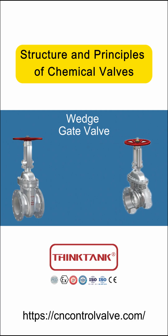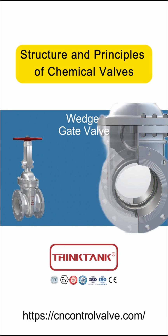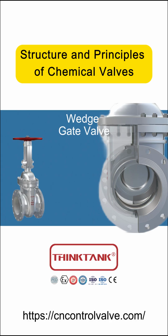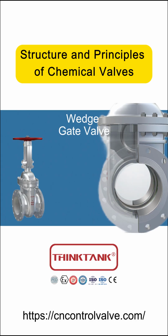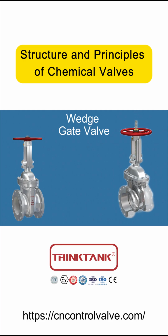However, it is more prone to seizing after prolonged use. Adhering deposits and hard particulate impurities will damage the sealing surface. The cleanliness of the media directly affects the valve's service life. Gate valves have almost no regulating function. Like ball valves, they can only be used fully open or fully closed. In a partially open state, it will cause significant vibration and impact, damaging the valve seat seal and reducing its service life.